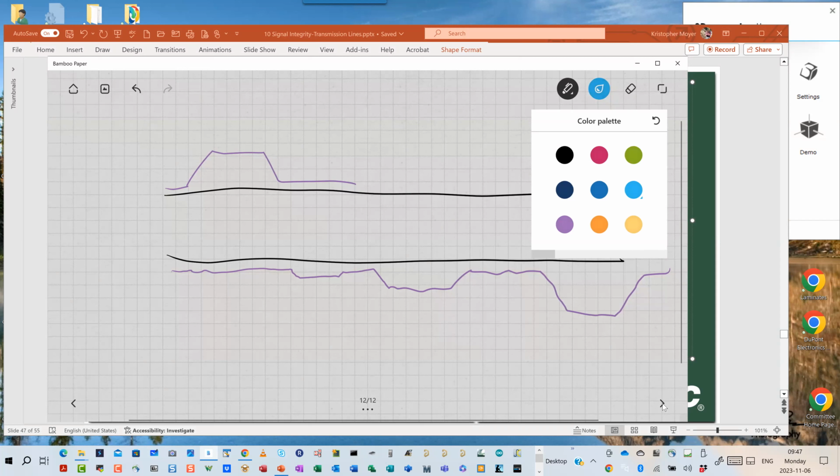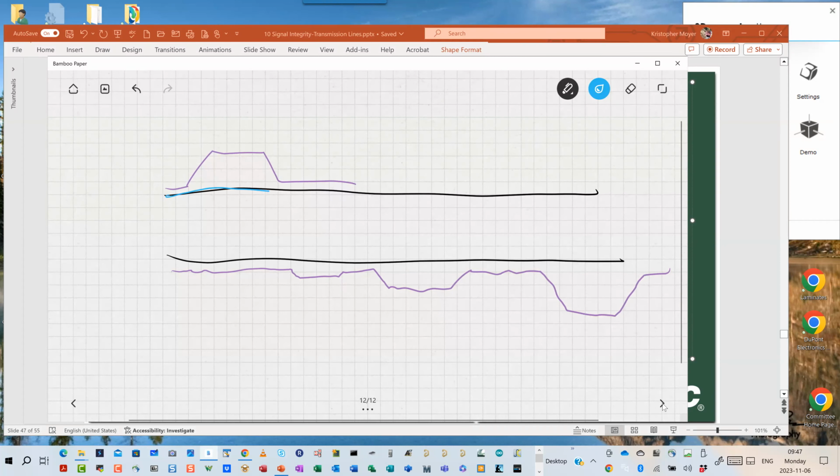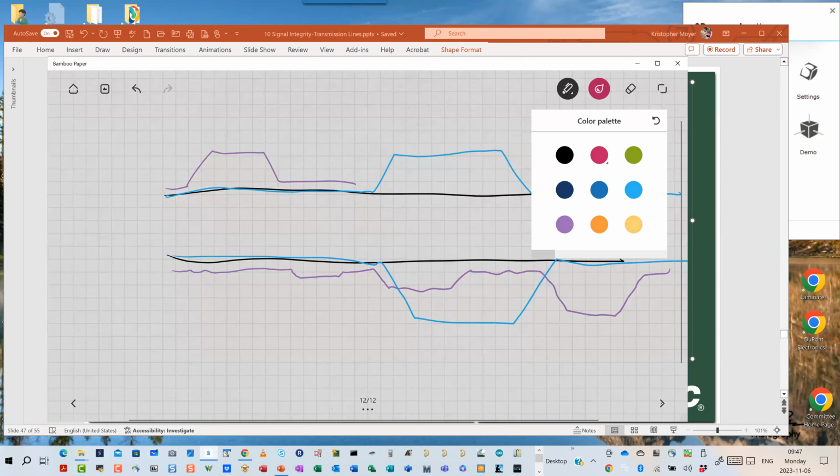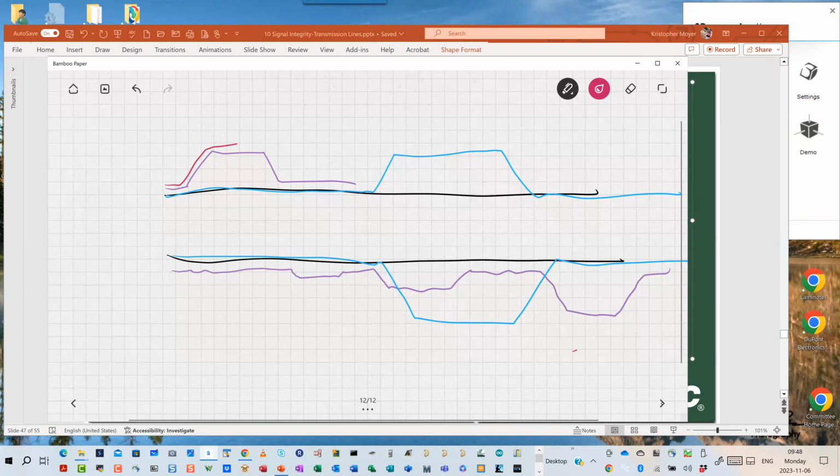Well, what if I take this net right here, and about halfway through, I split the nets, and maybe I double their distance for a while. Now, if I use red, again, we're going to have the same net, and I should have drawn the other one here. But by the time I get back over here, I've gone flat again because I've increased the spacing, so I no longer have that amount of coupling, to the point where when I get back here, I have to start back over from zero again, right?